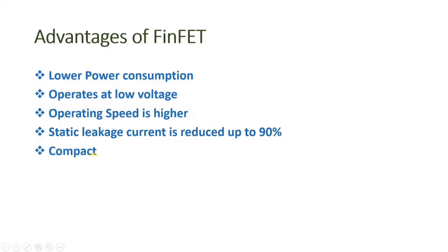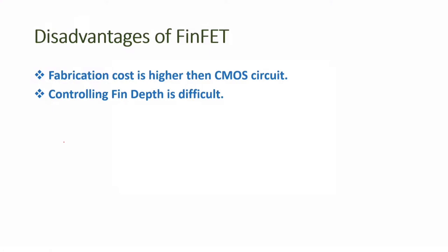So what are the advantages of FinFET? Low power consumption and operates at low voltage. Operating speed is high. Static leakage current is reduced up to 90%. And compact. Okay, these are the advantages of FinFET.